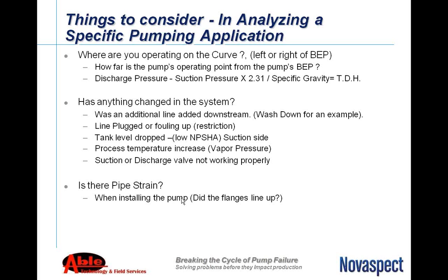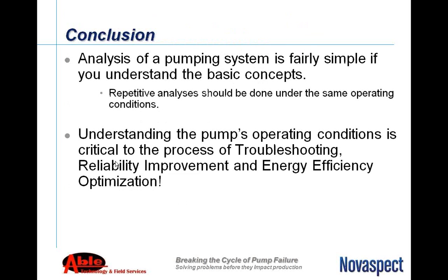And if you have to be down there when they're taking this pump apart, watch to see if those suction lines or discharge lines are jumping away. So by answering just a few questions, it will lead to increased mean time between failure. So the conclusion: an analysis of a pumping system is fairly simple if you understand the basic concepts, and I hope I've given you enough, not to get yourself in trouble, but enough to go down to your systems and take a look at them.